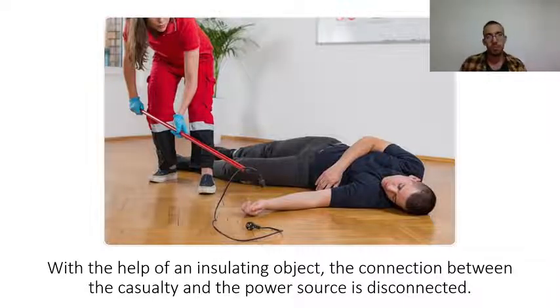we can use a stick. We can use our chair, for example, or I don't know, you can even kick that person with your shoe, if your shoe is obviously insulating. So there are options like that, and just get the person disconnected from the source. That's the main idea.